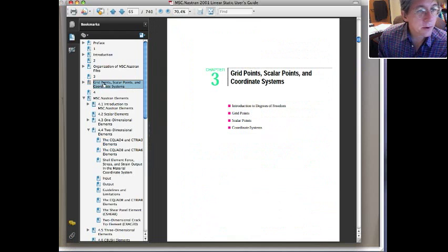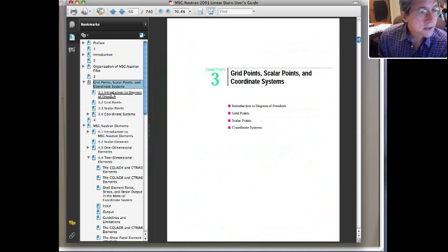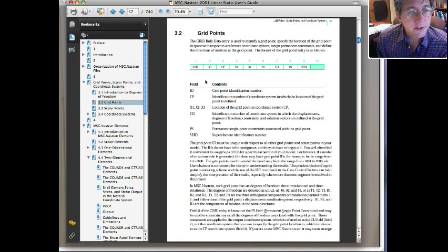And let's look at the grid point part just to see the definition. Now, if you look at the grid point part, we've used grid ID X1, 2, and 3. We've left field 3 and field 7 blank. So these have to do with alternate coordinate systems. All right. Now, field 3 is really a coordinate system just for defining the positions.